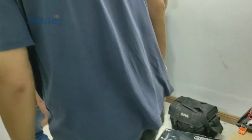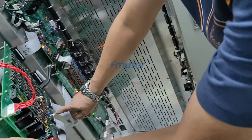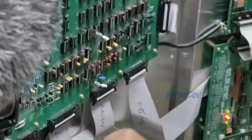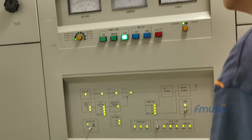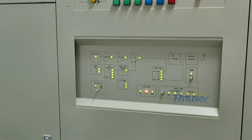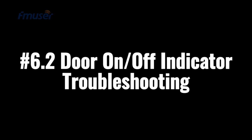To mitigate the risk, we first need to turn off the PA module as a precautionary measure. Locate the PA switch and lift it up to deactivate the PA module. Afterward, we can start the transmitter again. If the fan module is not functioning properly or has been damaged, the fan indicator light will turn red. This indicates the need to check the fan for any issues, such as a blown fuse, and consider if a replacement fan is necessary. Door on and off indicator light troubleshooting.